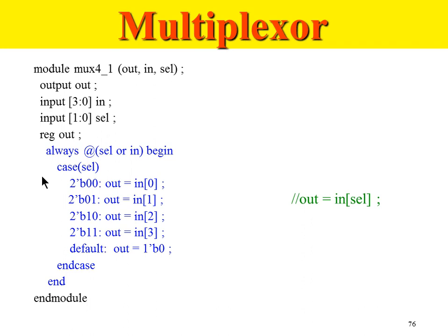So you either will be using behavioral modeling, where continuous assign statements are part of your modeling technique, or you will use structural modeling, where you instantiate the various gates or various components, do the interconnections, and create a purely structural model out of it. So ultimately, you will work on two methods: structural and behavioral.